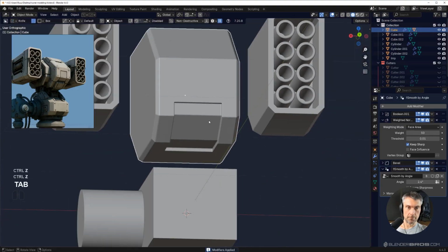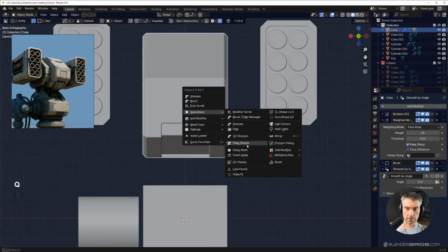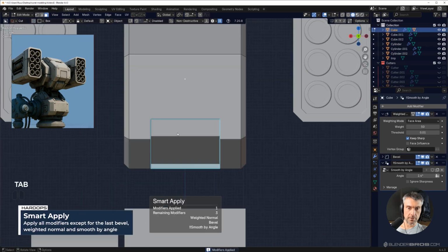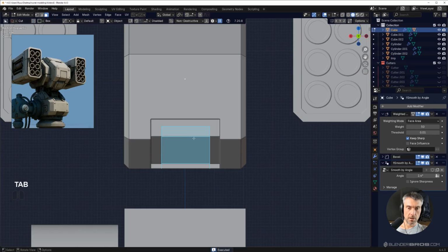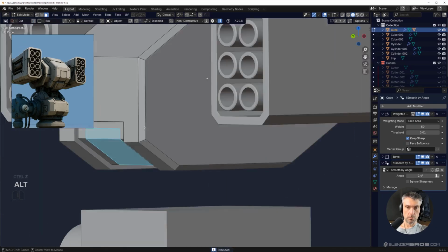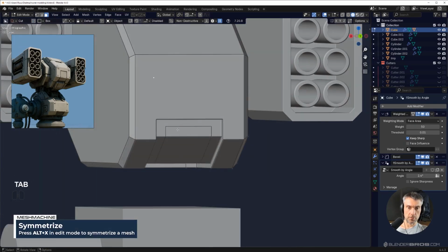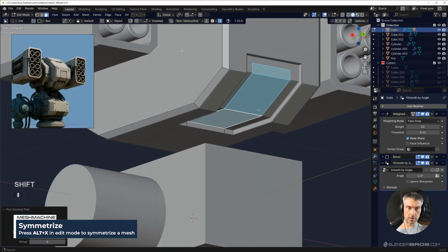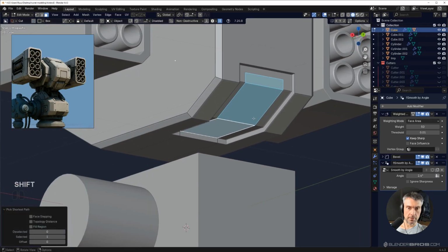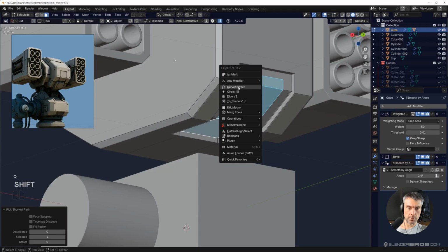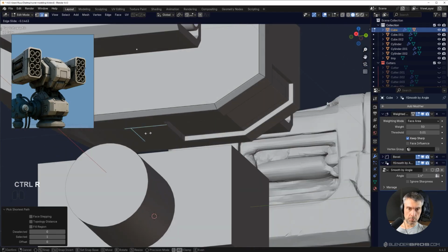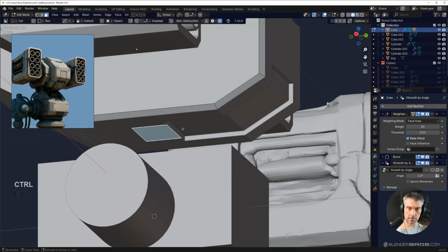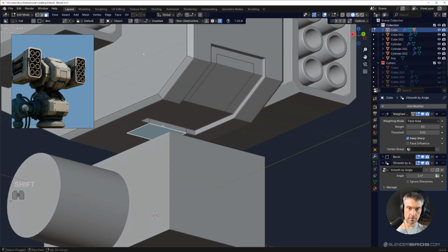Okay, that's better. Cool. So now let's apply this, and I'm going to run another cut here like this, right, with a knife. And we're going to mirror this with Mesh Machine again, so it's going to be in the middle. I just want to grab this element and shift curve extract. In fact, you know what, we could run another loop here, grab this entire thing.